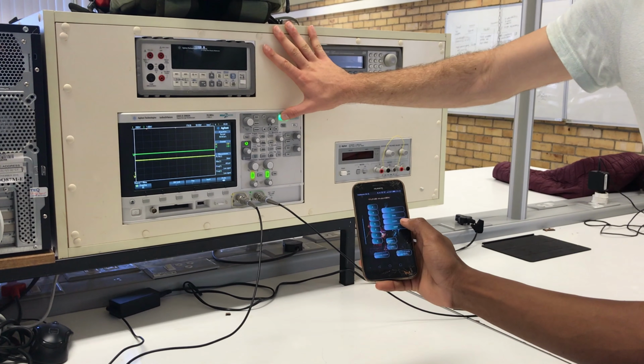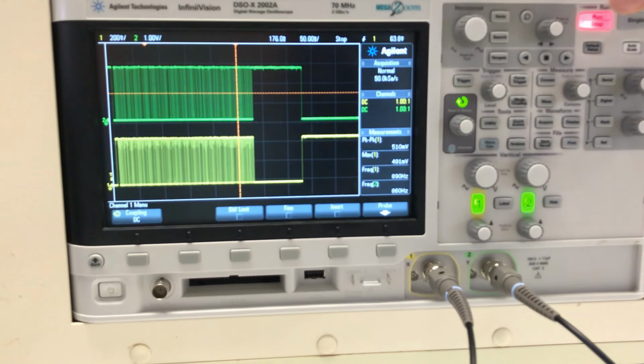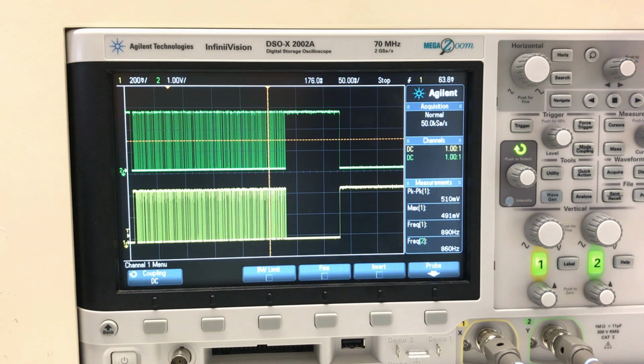Here, we can see the waveforms generated when the oscilloscope probes are put across the input to the transmitting infrared LED. The stop and start bits of the comms protocol can be clearly observed here. This satisfies system requirements 4 and 5.